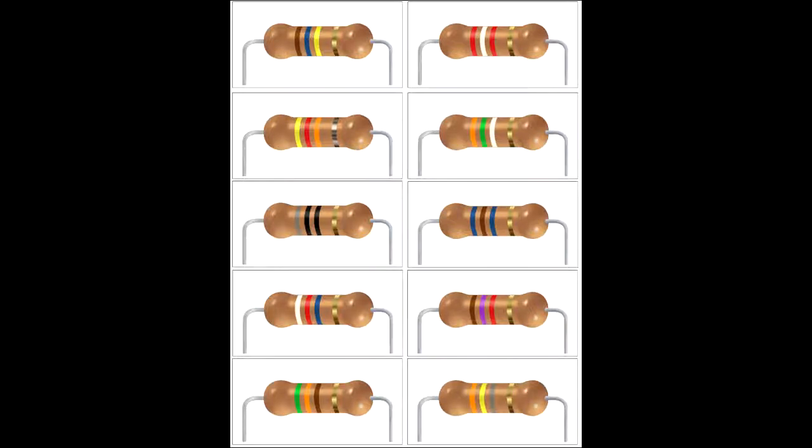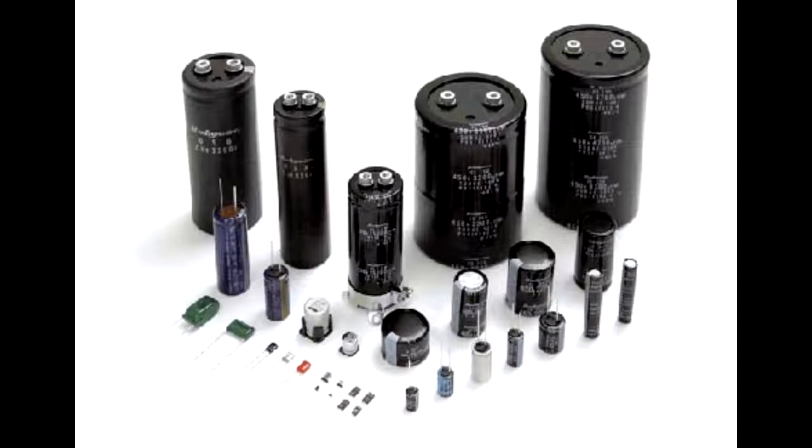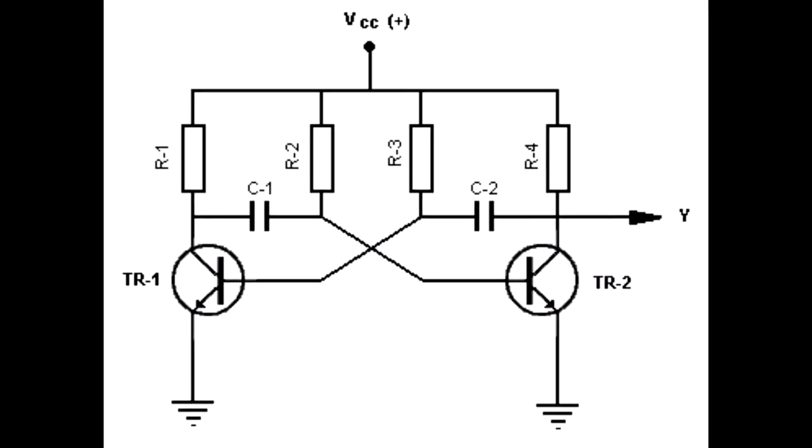The basic transistor circuit for an astable multivibrator produces a square-wave output from a pair of grounded emitter cross-coupled transistors. Both transistors, either NPN or PNP, in the multivibrator are biased for linear operation and are operated as common emitter amplifiers with 100% positive feedback.